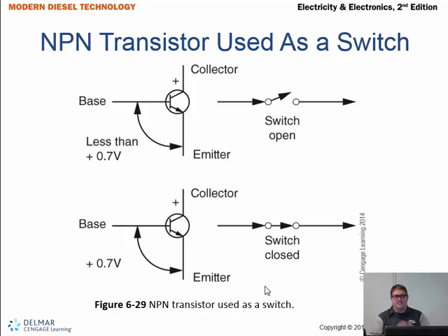Now this is something you're going to see all the time in our vehicles with smart switches and switches that no longer really carry current. The switch is just a signal to the module of driver demand. Instead of actually closing the switch and having current flow over that switch, it's just an input to a module, and the module is actually outputting that. So you will see this quite often inside of our current model vehicles.